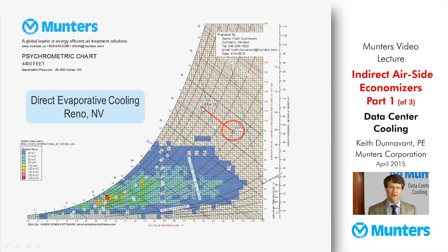This has cooled to about 66, but you'll see that I've also plotted the TMY3 weather data, hour by hour, plotted in bins for Reno. So you'll see that this extreme is well outside of what you'll typically see. Normally on a hot day, you'll be at a much, much lower dew point. You can then ride that wet bulb and maintain a 75-degree temperature, so you can get even cooler and stay below the recommended dew point and recommended relative humidity range.